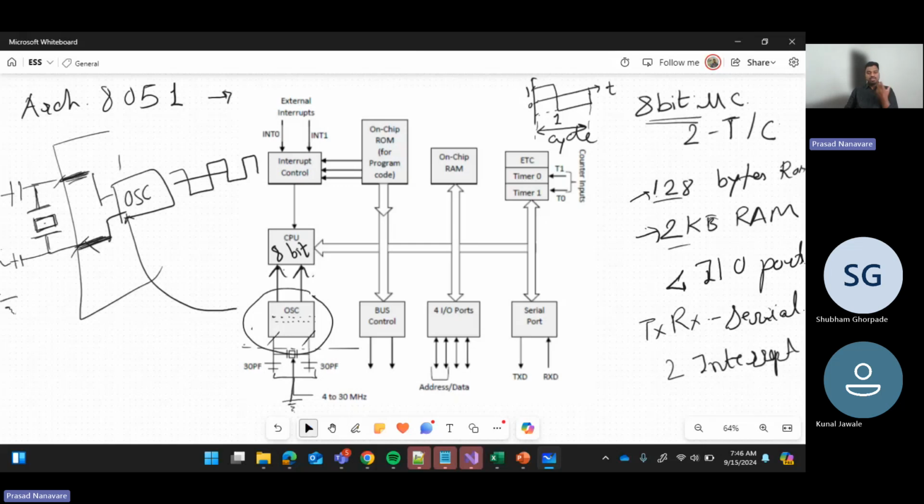So now our CPU has a constant clock cycle, and it is able to process 8 bits per clock cycle because the capability of the processor is 8-bit. Our processor is an 8-bit processor, right? Now what next? What are all the things inside of this little controller that we are going to look at? So here is something you can call bus control. What is this bus control? What is this bus? Now we'll see that.